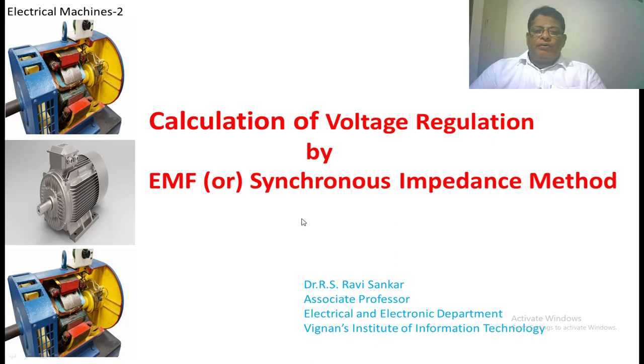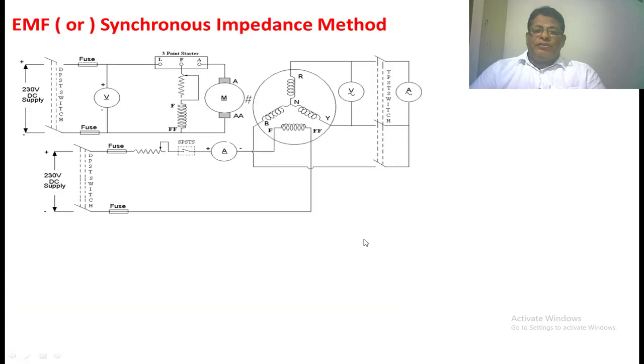In this lecture, we are going to calculate the voltage regulation of a synchronous generator. In this method, we are going to conduct an OC and an SC test on a synchronous generator. OC test is nothing but the open circuit test. SC test is nothing but the short circuit test. First, we are going to see the open circuit test.